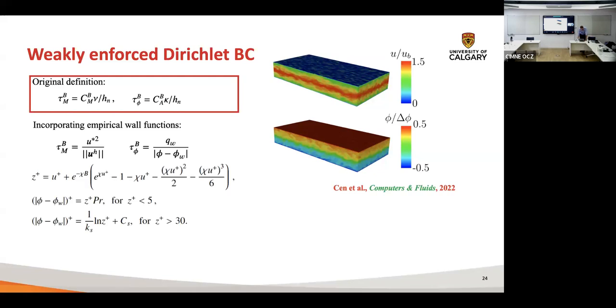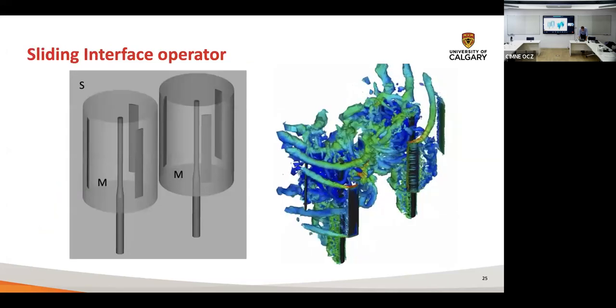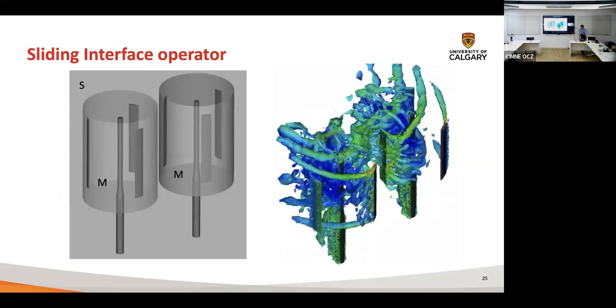So we can also use the actual wall model weak BC. We recently extended that to wall modeling for the temperature, and we also incorporated the wall roughness into the weak BC formulation. I will show you cases where having the wall roughness and the wall model weak BC is critical. Otherwise, you would not get anything in your solution. Now, I will probably skip this part.